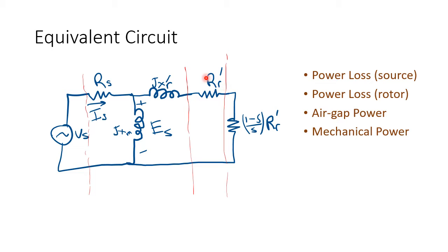But there's also that magnetizing resistance, because if the rotor is spinning relative to the stator, then what's going to happen is that there will be some magnetic force being applied, and in other words, that's going to produce a back EMF, which can be counted as resistance. So if you decide to use this equivalent circuit model, then you will say, okay, this side is the resistance that is caused by the back EMF magnetic field, which we can equate it to being a resistance R.